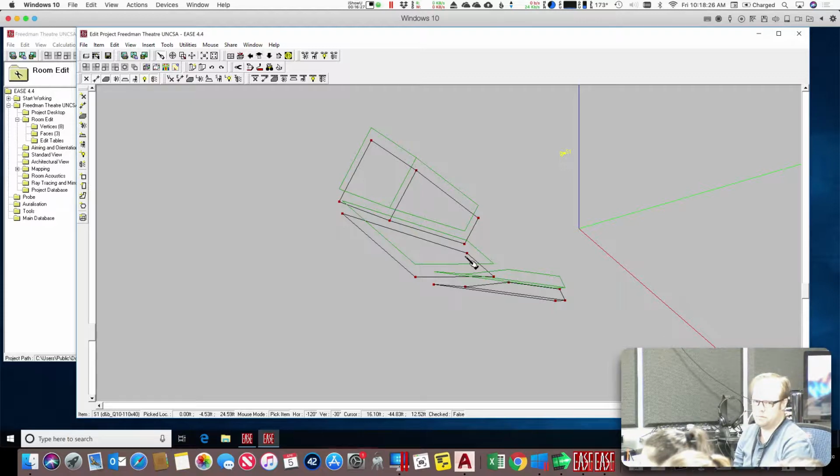That saves you a ton of time for drawing, but you can run into problems with that when you start putting certain loudspeaker models in here, because just the way that the data is organized in that loudspeaker file makes it really difficult for EASE to plot the data. I suspect, and I don't know this for sure, that one of the ways the EASE loudspeaker format can be set up is you don't have to put values in for the full 360 degrees on every axis sphere. You can just do what they call a quarter sphere, and then tell EASE to infer the rest of the coverage based on what's in that quarter sphere. I think that's what's happening when they say it's asymmetrical in a symmetrical room: there's something about that quarter sphere symmetrical data that makes it not able to calculate that. I don't understand why fully, but it is.